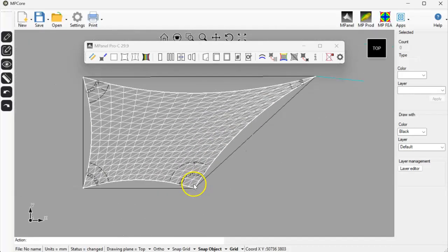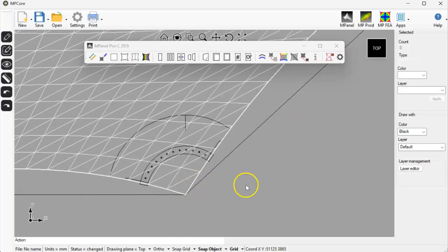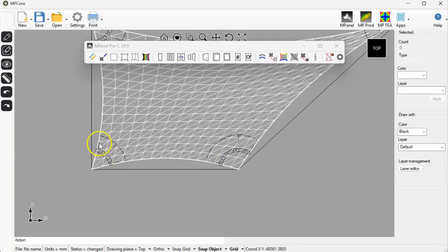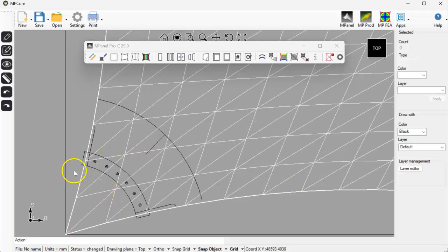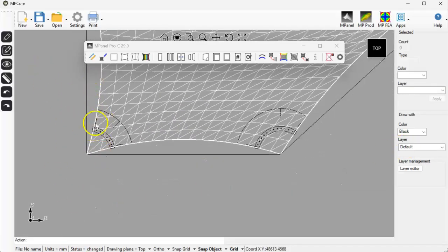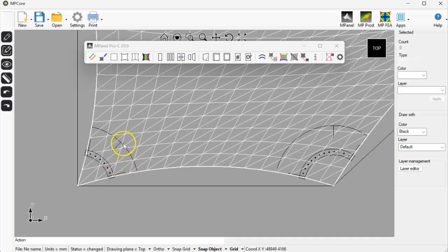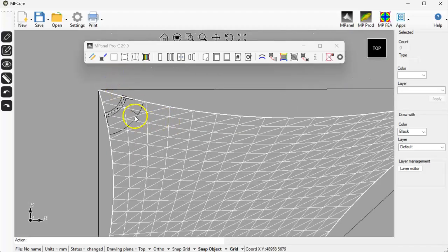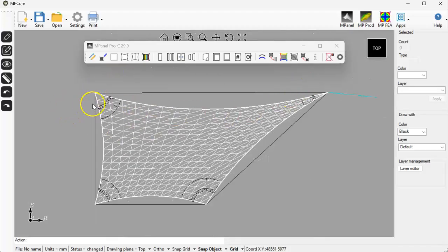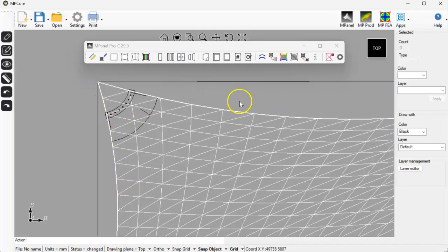And as we anticipated, here we've got a longer side, higher tension than we do on this edge, and therefore the reaction is going to swing towards the longer side. Here the forces are equal, a 90 degree corner, and the same distance on each side, so the same cable tension. So here we can see the reaction angle is estimated to be in the middle. And again here we've got a longer edge and a short edge, higher tension on the longer edge, and so the estimated reaction angle swings towards the longer side.